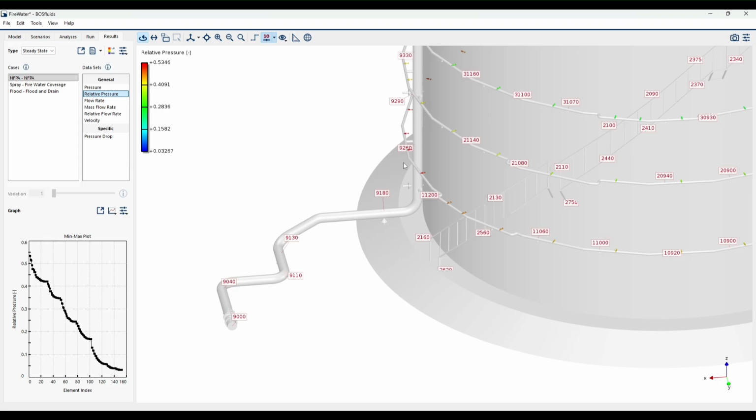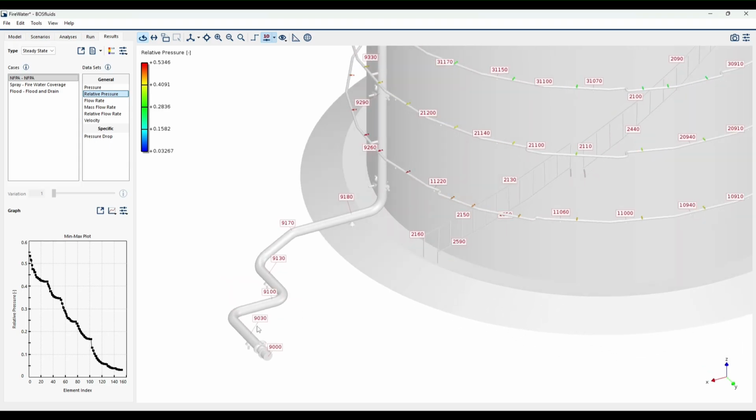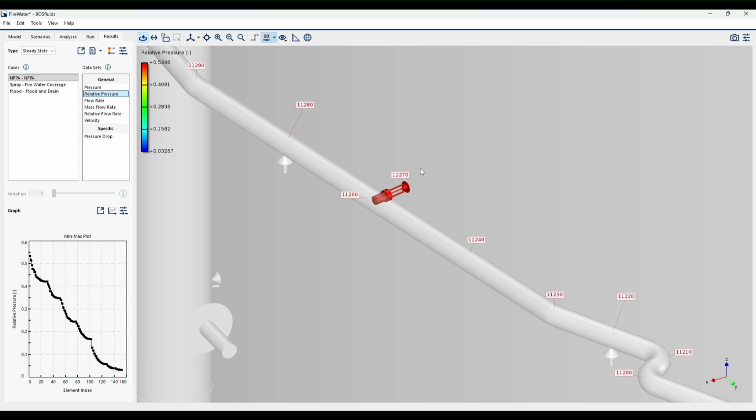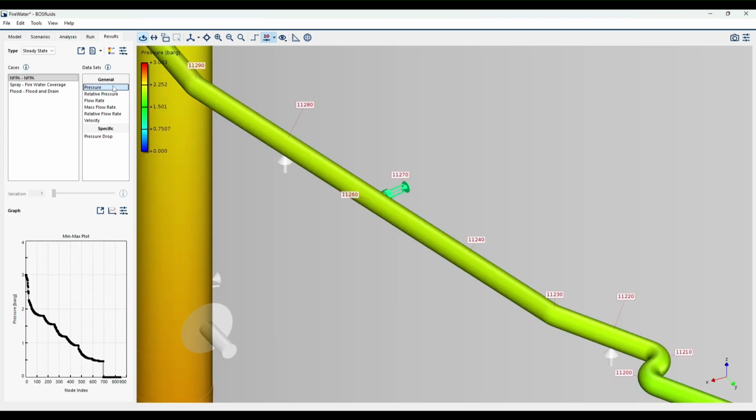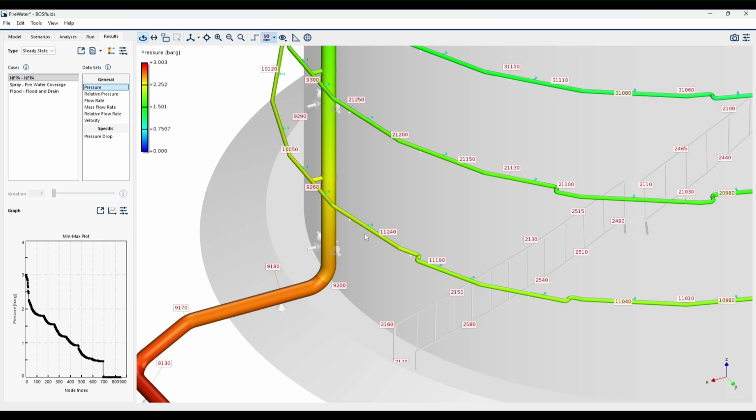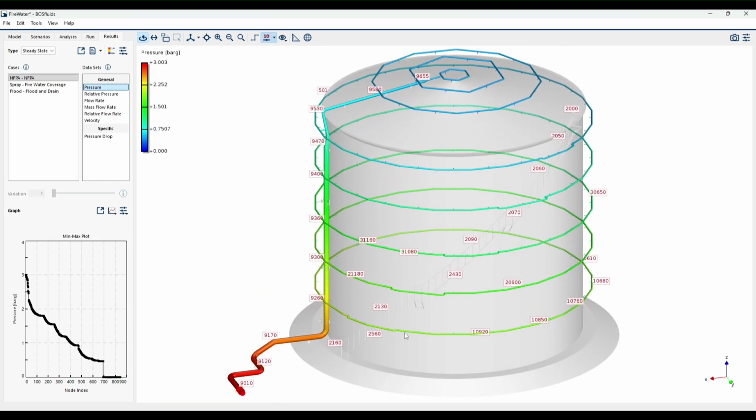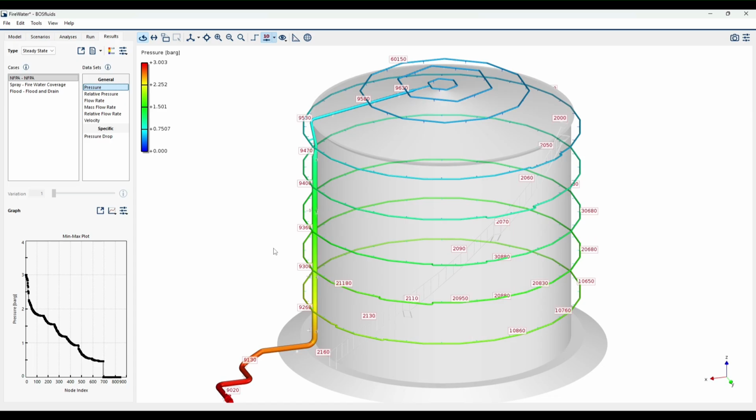And the red ones here, as we expect, because they are closer to the supply node, they are closer to the maximum pressure, which I believe is 3.8 bars. So if we go here, if we select the inlet, 2.1, so almost half of 3.8. Okay, or a little bit more than half. But okay, now that we have said that, the NFPA is fine.